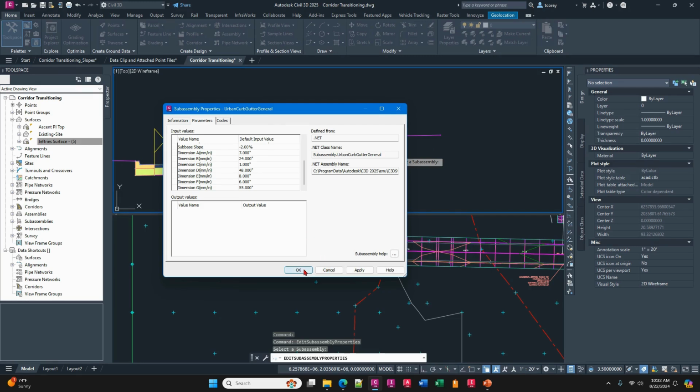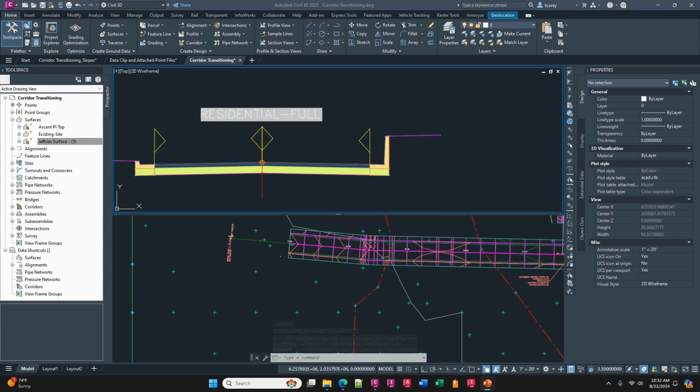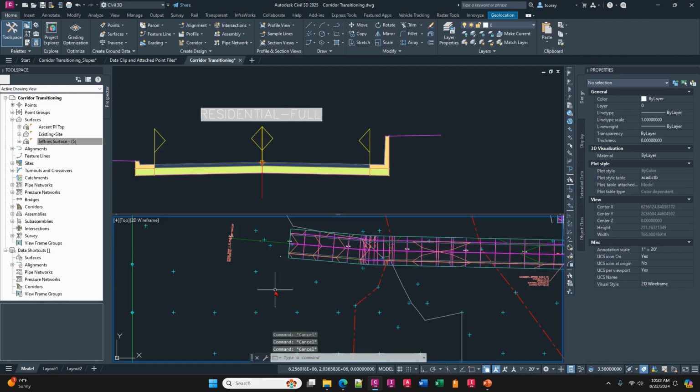Can you please go over the other Xref variable setting related to demand load Xrefs with copy? Xload control is the AutoCAD setting. Let me show you in options. In AutoCAD options, I just type OP to get there.